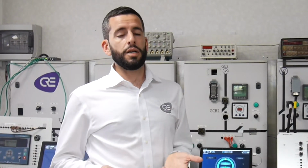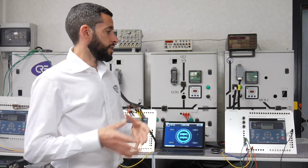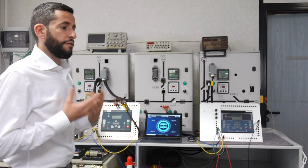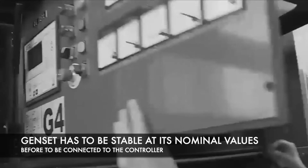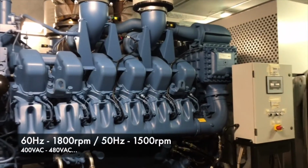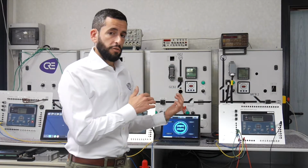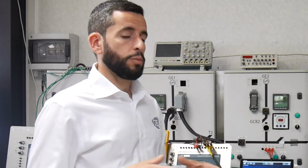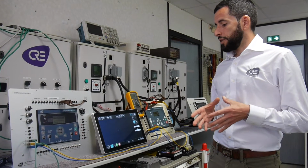This is just like when you drive your car: if you have flat tires or a broken engine, you won't be able to drive your car. It is the same with EasyCalib. So first, whether it's a retrofit or a new application, you have to make sure the genset is running fine: 50 Hz, 400 volts, nominal speed, nominal frequency, nominal voltage, and this is correctly adjusted from the factory or from a review.